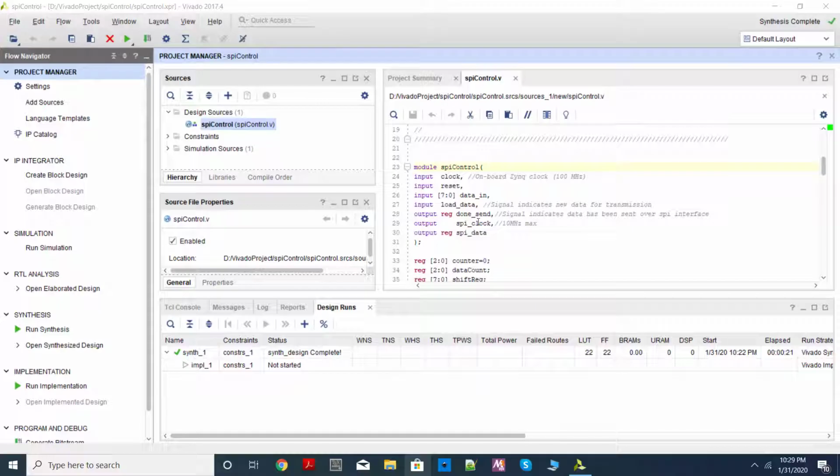So at runtime it will be capturing the data from these flip-flops. That information is also sent through the same programming interface which you use to program the bitstream as well as the ILA file. So all those things happen through the same JTAG interface. This is a very powerful feature. So let's see how to do this.